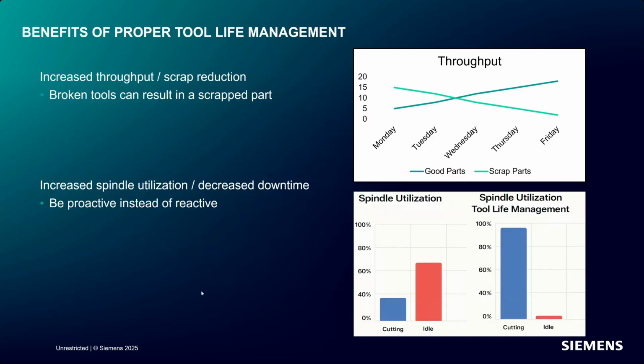This all stems from my time working at Smith & Nephew, which is a large medical device company. I was in the bone plates division, and all of our machines in the building ran bone plates, 700 catalog items, and the biggest tool we ran was a 1/4-inch end mill. With 35, 40 machines in the building running at one time, you can't hear a 1/4-inch end mill getting dull, right? So pretty much all the time, the only time we knew to change tools was when they broke.